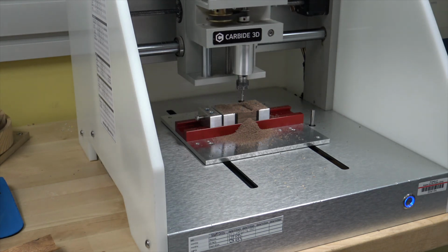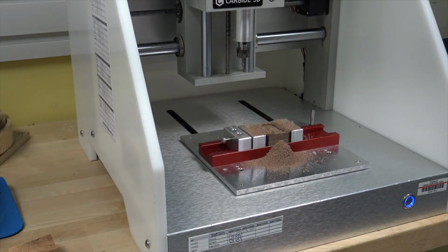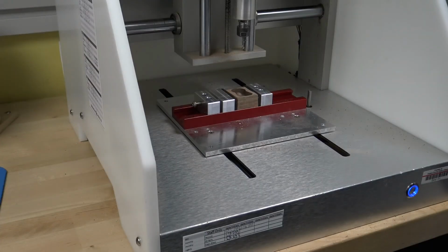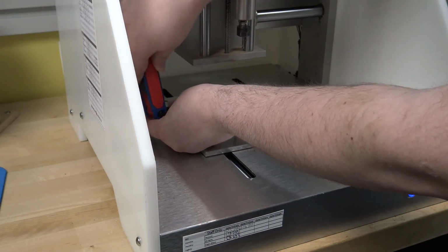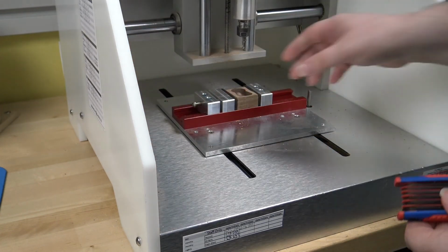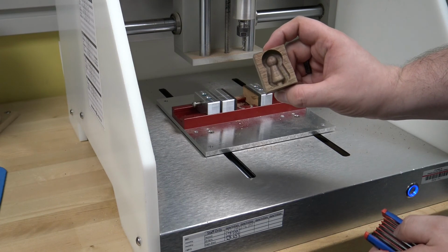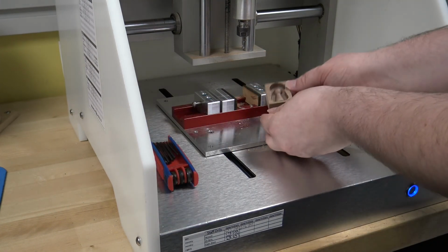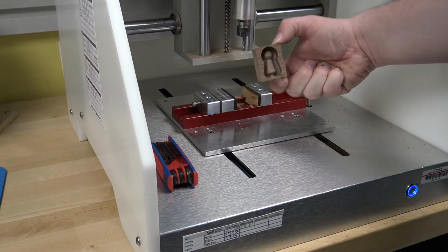Once the machine finishes, the piece will slide forward and the mill will stop moving. Clean off your material with a vacuum located beneath the machine. Use a hex wrench to loosen up the jaws and remove your piece. If you are doing a flip job, make sure to rotate your piece laterally and place it back in the clamp's jaws, then re-tighten.